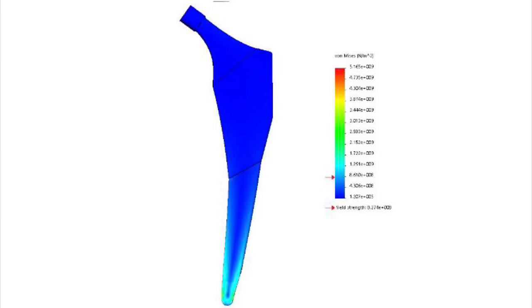From the results which I gathered, I managed to see that the stem that I created is not weak, it's strong in terms of it can bear the loading which I used, which again is 2000 newtons, and it doesn't seem to show any break points at all on the stem, which means it's a good stem to go ahead and do the pore structure.